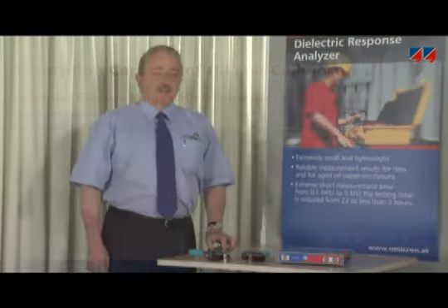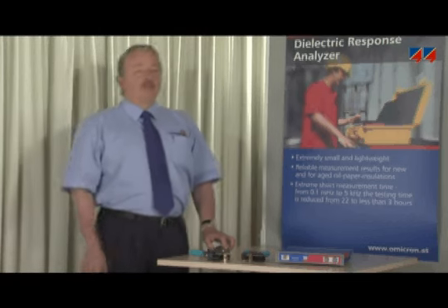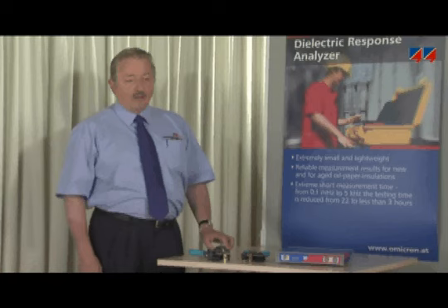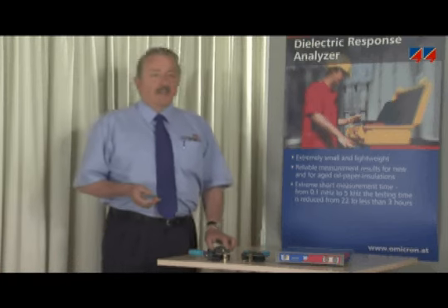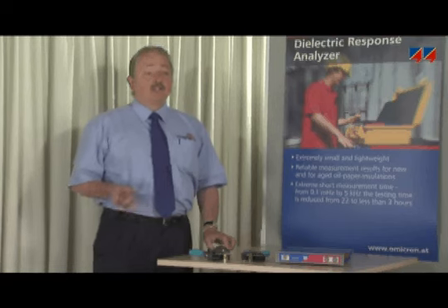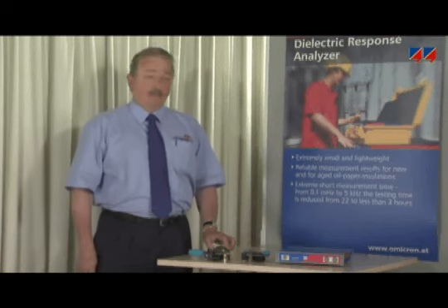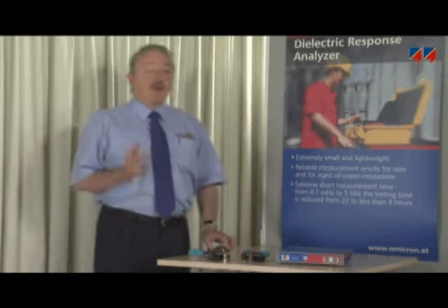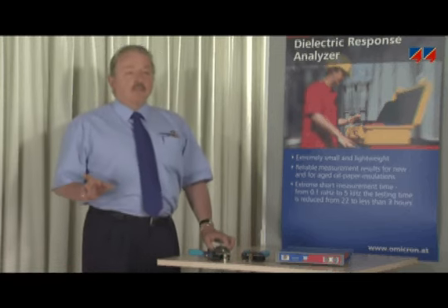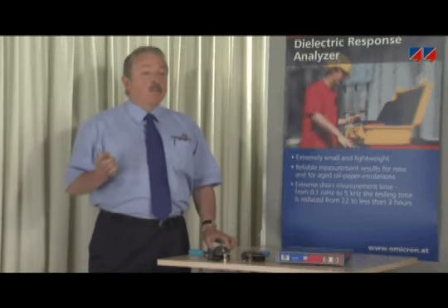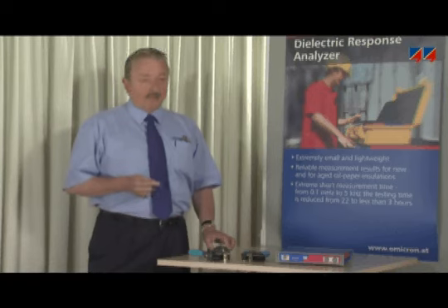There's a process running in a transformer which is called moisture diffusion or moisture thermodynamic equilibrium. Every system tends to reach equilibrium. Moisture equilibrium is driven by differences in water potential. This approach is very theoretical, but it can be broken down to a very practical approach. The relative saturation of adjacent materials becomes equal under equilibrium conditions, providing that the same temperature and pressure exists.